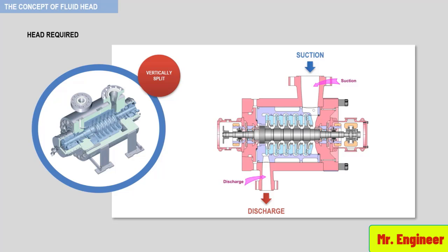leads to a much greater emphasis upon the compressor's mechanical components, like the impellers, the labyrinths, the seals, the bearings, and the shafts. In many cases, the root cause of dynamic compressor mechanical damage is that the head required by the process system exceeded the capability of the dynamic compressor.